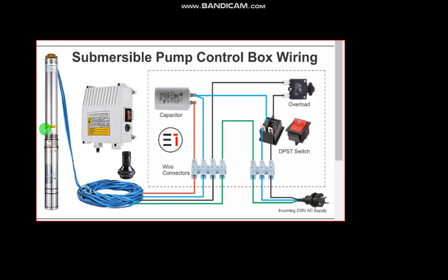From the winding formation of this motor, after the wiring and the connection of the windings, we have three conductors out to terminate to the terminal. That is these three conductors. One of them is live conductor, which is this one that goes here and supply. The second one is the neutral. Then the third one is capacitor line, capacitor permanent. One is capacitor line, one is capacitor permanent, and one is line. Line is this one, goes direct. Then neutral also go here and supply. Then the capacitor permanent come out from the motor and remain here.